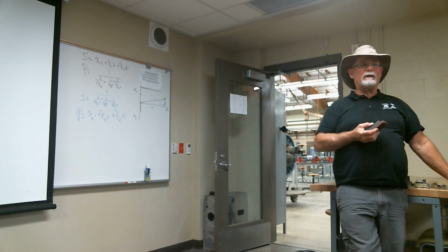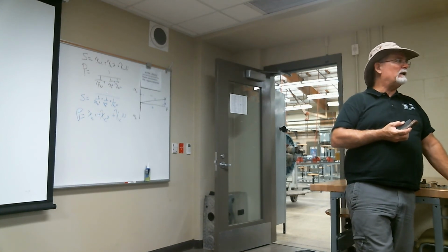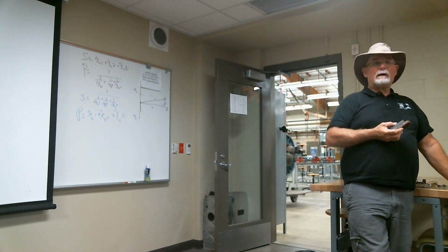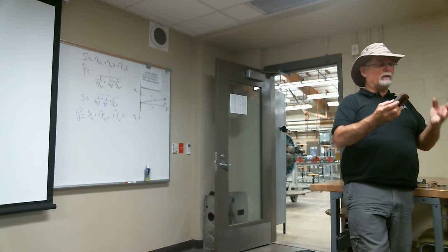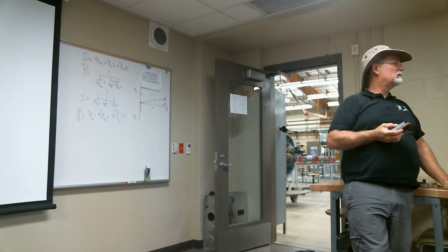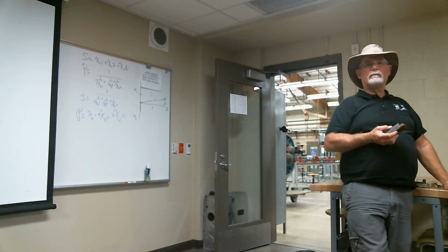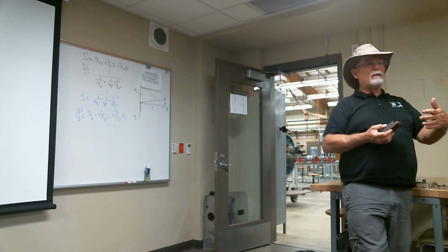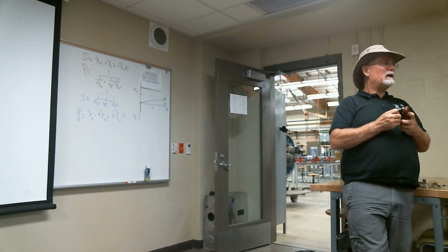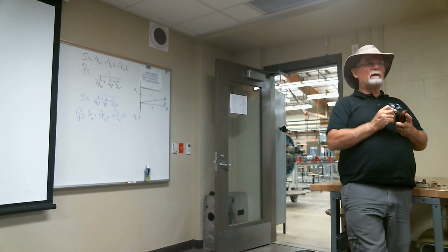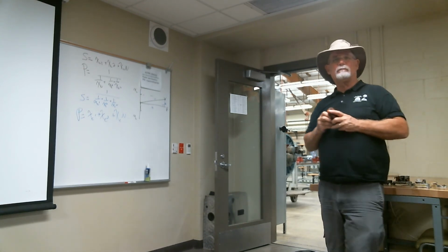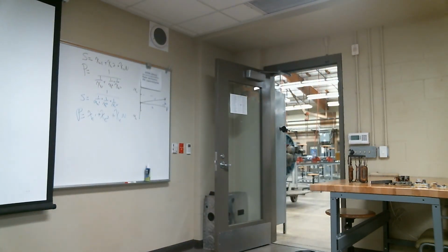In the case of power generation, we typically are going to give you ratings of voltage and amps. Why? Because ultimately you're going to have to install this unit in light of a bunch of users on the bus that are also measuring amps. And you got to make sure that your generator puts out more amps than all the users can consume. So they have a tendency to do it that way, even though you could use power, right? The problem is you'd still have to have voltage. Because I can't put a 28-volt unit in a 12-volt hole. That would make for a big mess.